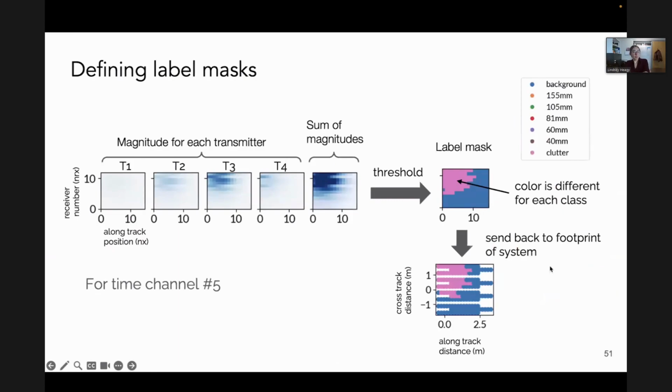An important step for this is then saying, okay, how do we actually generate our training data where we say this signal is associated with UXO versus not? When you're thinking about an image with a horse in it, it's very easy to draw that outline. But when we have EM data, we have a peak and then it decays away. So we needed to pick a strategy based on thresholds.